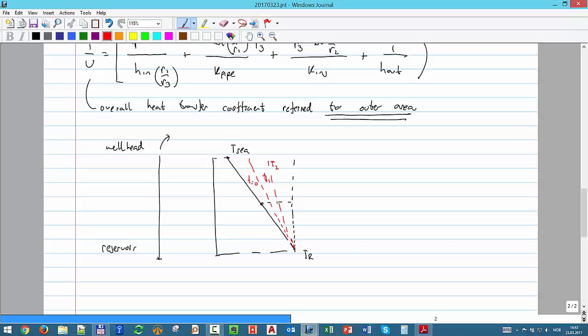It will reach something in between the original geothermal gradient and the temperature of the fluid, which of course is not constant. So that will be the temperature of the fluid, and that's the temperature of the formation far away from the well, and the near wellbore will be heated by the flow in the well.